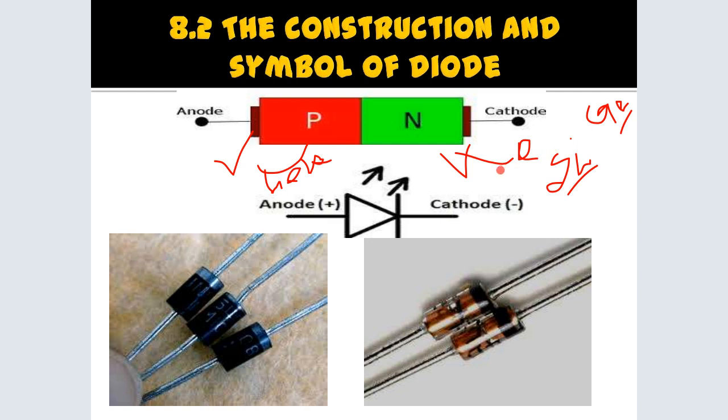From bonding, or from the previous content that I had issued, if you want to get excess electrons, then you're supposed to use a donor. If you want to get excess holes, or rather a deficiency of electrons, because that's what a hole is, a lack of electron, then you use an acceptor. Depending on which element you choose to use, it will give you an outcome that is either a P or an N-type material.